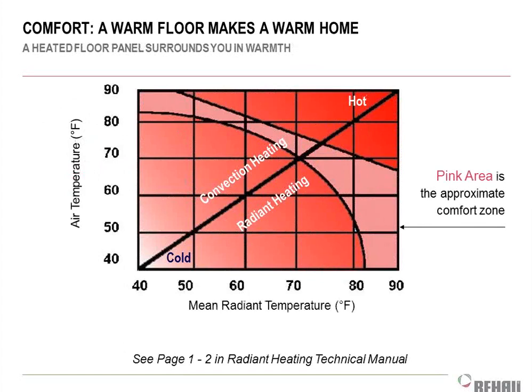This kind of gives you an example of just looking at the air temperature and radiant temperature portions of the ASHRAE standard 55, and kind of ignoring humidity and all those comfort things for the moment. So if you look at it here, on the left scale, the vertical scale is room air temperature from 40 to 90, and mean radiant temperature, meaning average radiant temperature from 40 to 90, of my surfaces in that space. Those pink bars are when you graph out the ASHRAE standard to graph out when people are actually comfortable, right?